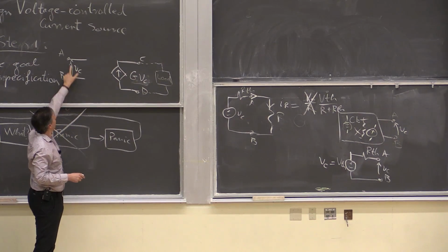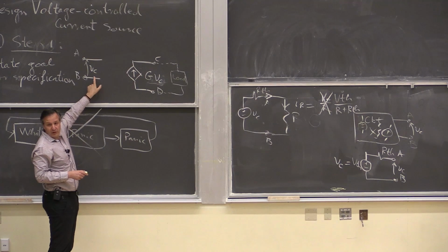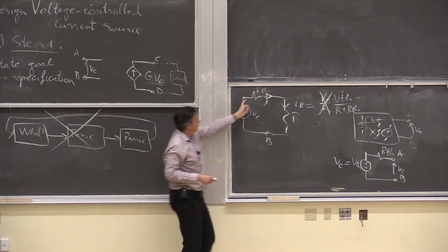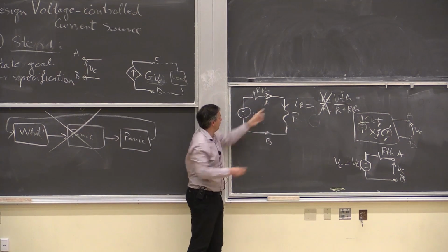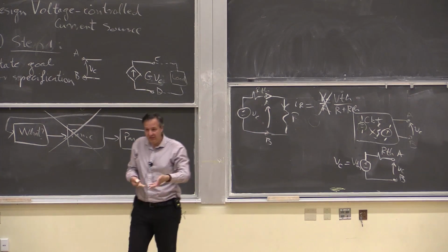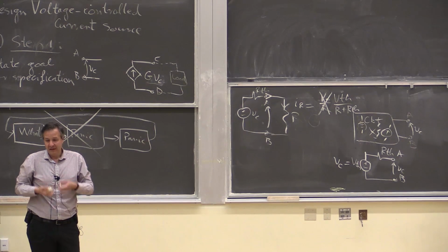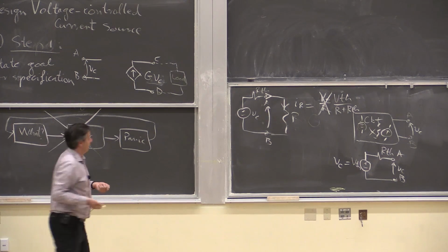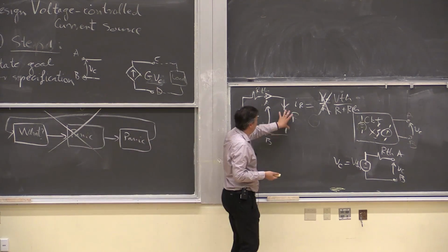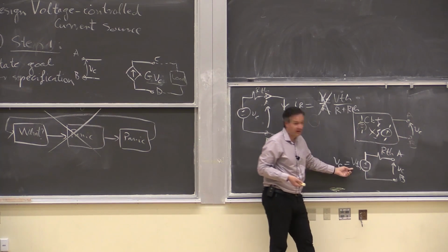We wanted to do a measurement with an open circuit, right? So by establishing this current, this voltage here is no longer equal to VC. It's some divided version of VC. So I haven't really done the right thing. My objective was to have this current be driven by this VC voltage, which is actually VThevenin.